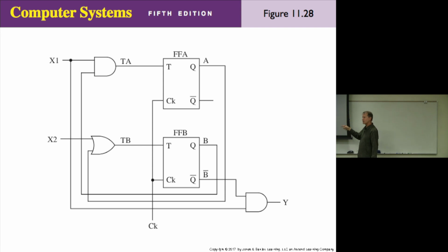And for each one of those, the states could either be 0 0, 0 1, 1 0, or 1 1. So do you understand what we have to do to construct the state transition table? There are 16 possible transitions, because there's a transition for all possible states, and for each state, all possible input combinations. Is everybody with me?